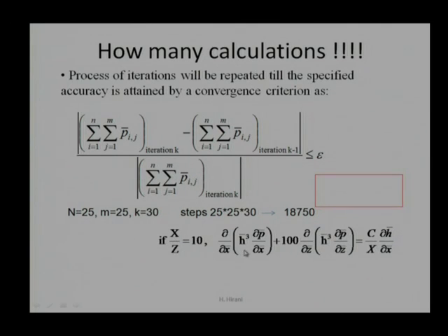However, if we take an approximation, the reason being that the dimension is very large in x direction compared to z direction, in that situation the second term will be dominating. It is 99 times higher. Then this term can be neglected to reduce the number of steps. If we neglect this term, we require only the number of nodes in z direction. We do not require any node in x direction as it is independent, and due to this the number of iterations will reduce.